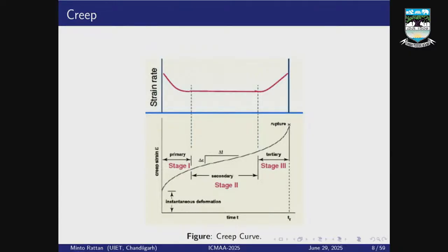Although it was recognized that the secondary stage was very short by comparison with most pure metals and solid solution alloys, by contrast, some metal matrix composites exhibit creep curves where the secondary stage is more linearly delineated. The close similarities in the creep curves of unreinforced powder metallurgy materials and metal matrix composites provide support for analytical or theoretical treatment of creep results for metal matrix composites in terms of the steady state creep rates.